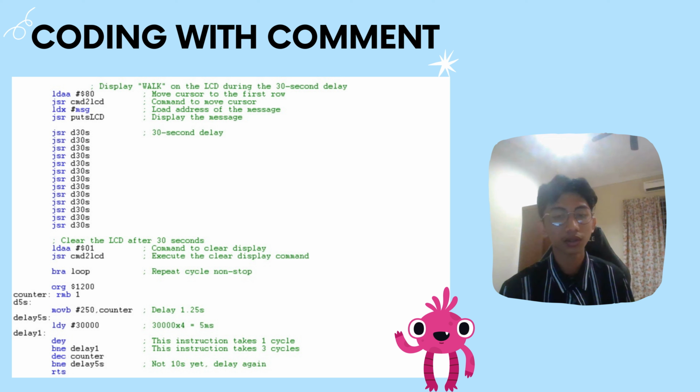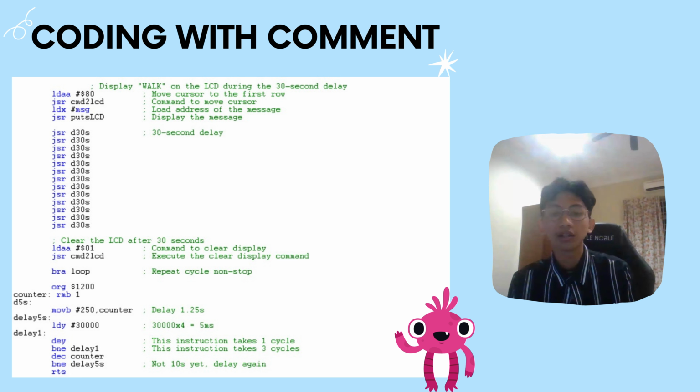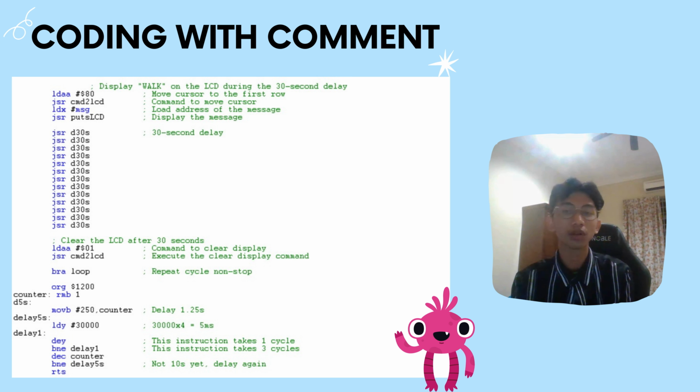So this code clears the LCD every 30 seconds and implements a delay subroutine, which is the delay 5S, that creates a 5-second delay using nested loops. Where delay 1 produces a 5 millisecond delay, delay 5S repeats it 250 times for 1.25 seconds. And delay 5S runs multiple times to reach the required delay before allowing the program to continue.